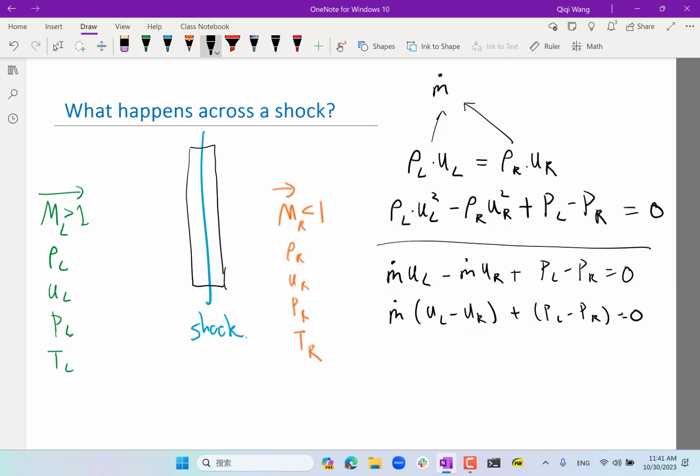So this makes the work of the shock wave more explicit. It is trading velocity with pressure, right? One of these is positive, one of these is negative. Somebody tell me which one is positive, which one is negative. The velocity term is positive and the pressure term is negative. We have a high-speed flow going into a shock wave. Just remember the car video, right? There are cars traveling at high speed over here. It bumps into the shock wave, it stops, and it becomes low speed.